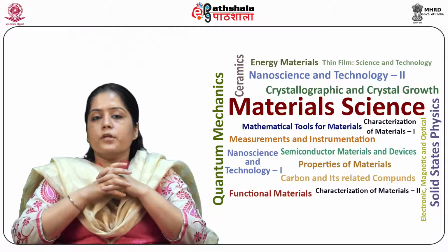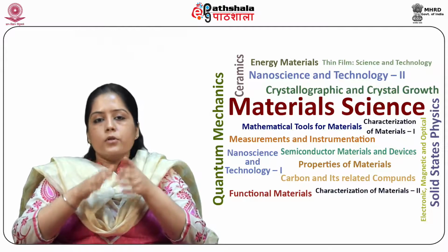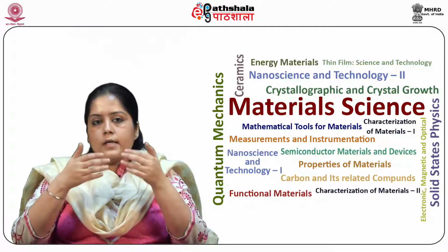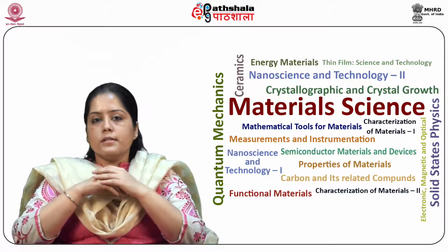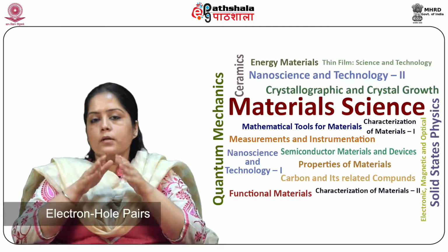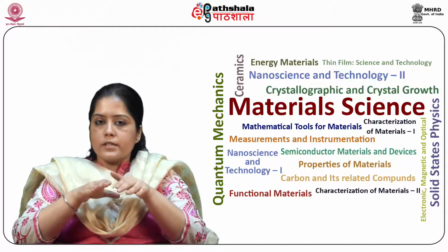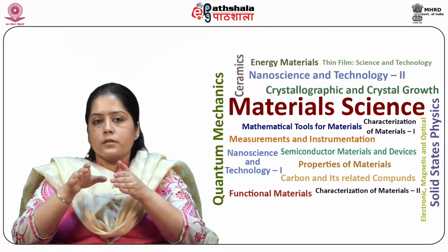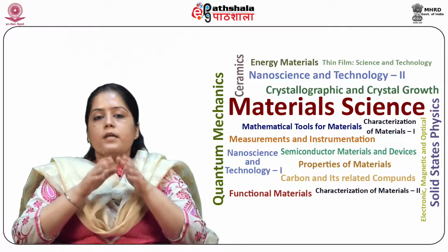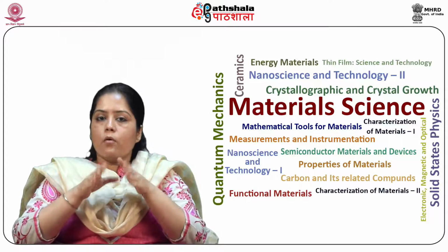Let us start with a brief introduction about the module. Photons of energy more than the energy gap incident on the semiconductor will produce electron-hole pairs. If they are not stimulated to move apart, they will eventually recombine in a time dictated by the lifetime of the material.